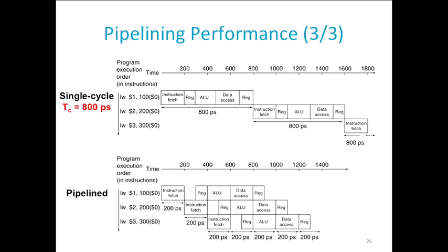But even so, we've gone from 800 picoseconds, which was the 1.25 gigahertz clock rate, to now this pipeline version. Cycle time is only 200 picoseconds, and there we are, running at 5 gigahertz now, right? It's a factor of 4 speed up from pipelining it over 5 stages, right? It wasn't perfect, but it's a big boost in performance. And so this is one of the big ideas in architecture, and one of the early ideas that really led to massive speed improvements.